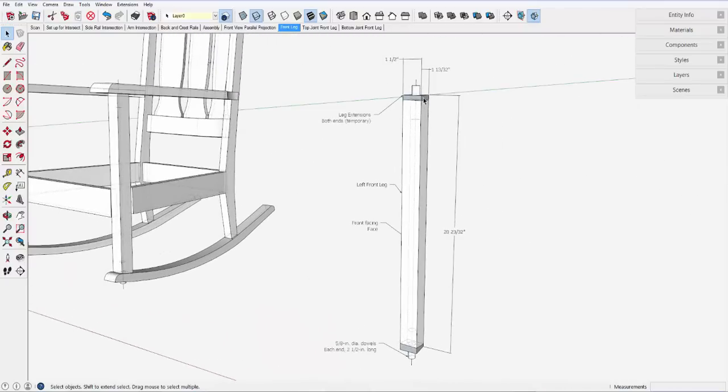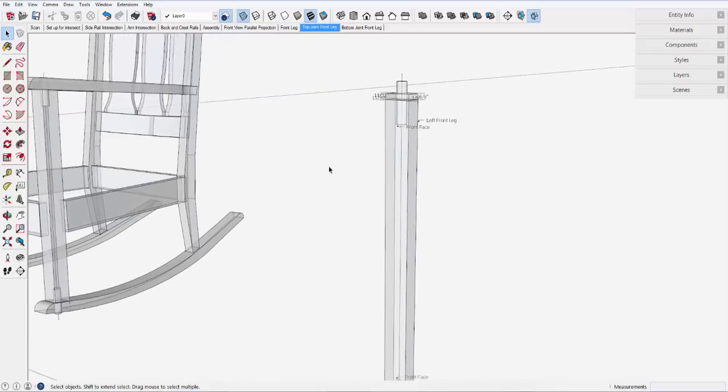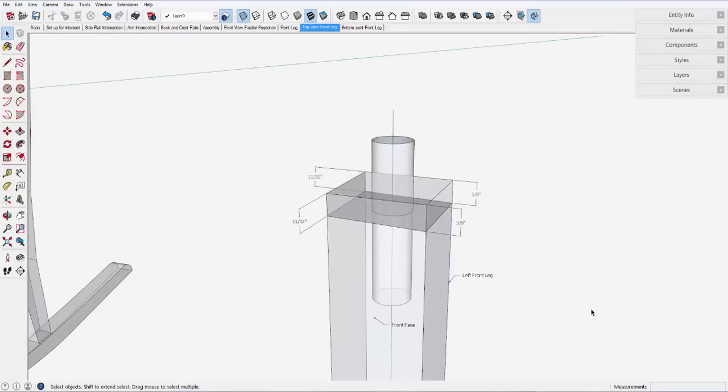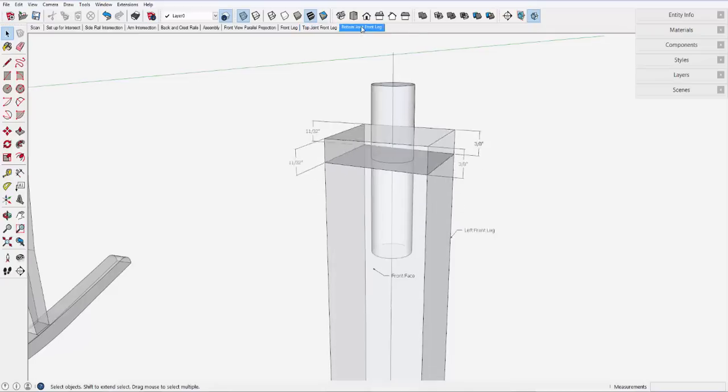work in the shop? So I created this dimension view, a perspective view of the leg blank with these extra extensions that make this leg blank cut off square at the ends. This allows me to determine critical dimensions to cut it. Here's the top view with some critical dimensions that I can mark out around the perimeter of the leg and make that compound angle cut.